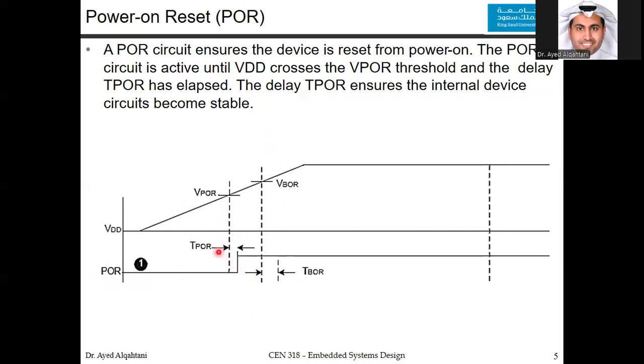Now, why do we need this TPOR, or this time? This delay ensures the internal device circuit stability. So it is just a safeguard for you. We have also another time for the brownout, but it's better to show it in the next timing diagram.